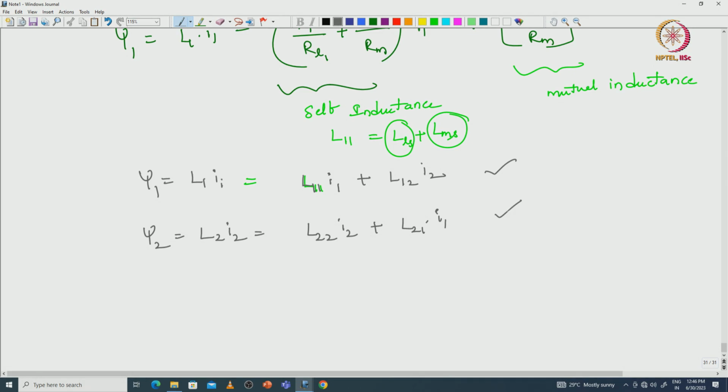The performance curves will not change with respect to the other circuits we have discussed, only the magnitudes will vary. This is the B versus H waveform. In the linear zone, mu will be constant, we will see the linear characteristics and there is no saturation. After that we will see the saturation, where the mu value is almost equal to 0 and B will not change, and only H will vary.